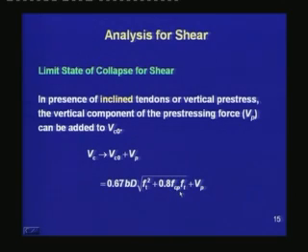This full thing is the shear causing the web shear cracks plus Vp, which is the vertical component of the prestressing force for an inclined tendon.